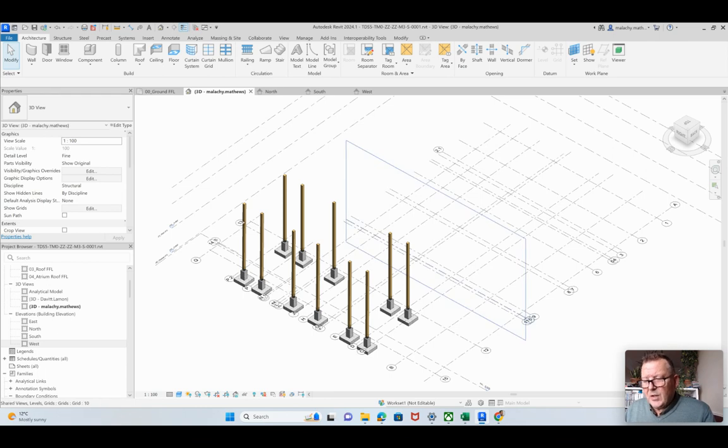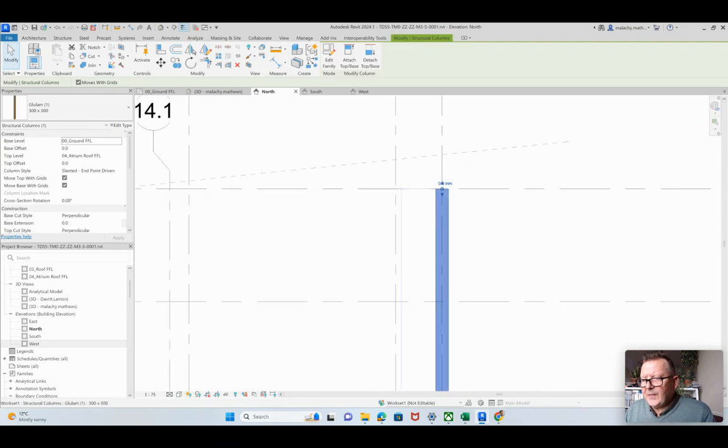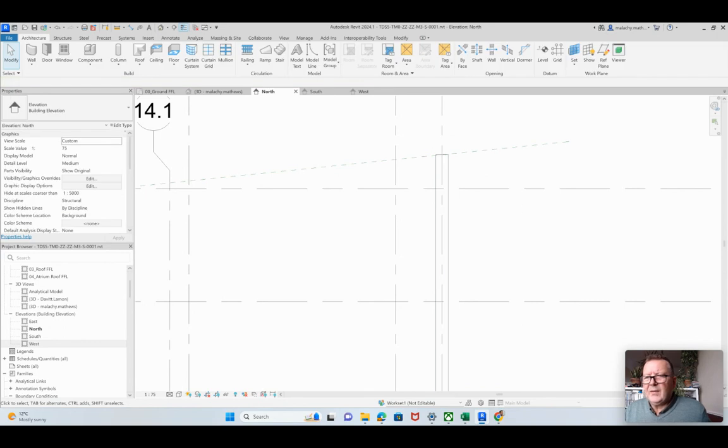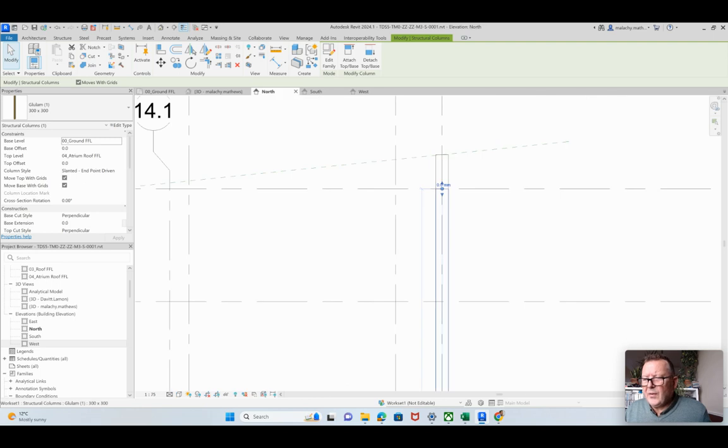So if I'm going to create the slope with the joists, then I need to raise up each of these columns here to meet that one there. Now, what I can do is pull this one up until it gets up to about there. It's telling me it's 817.9. I don't want that. I'm going to do this 820. Now, I go into each of these, pick that one, go back to the north, and again, all I need to do is change the figure here, 820.